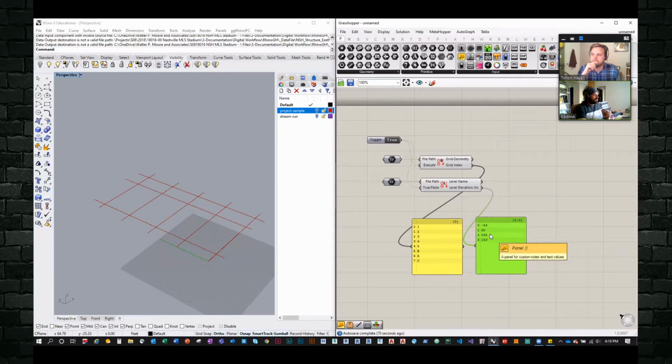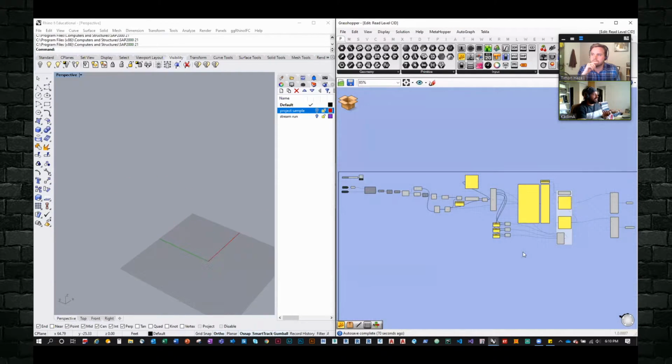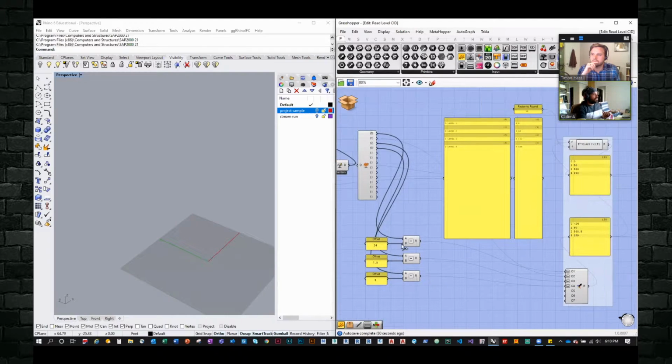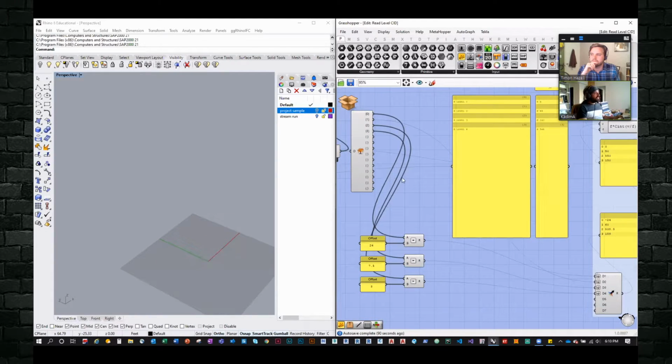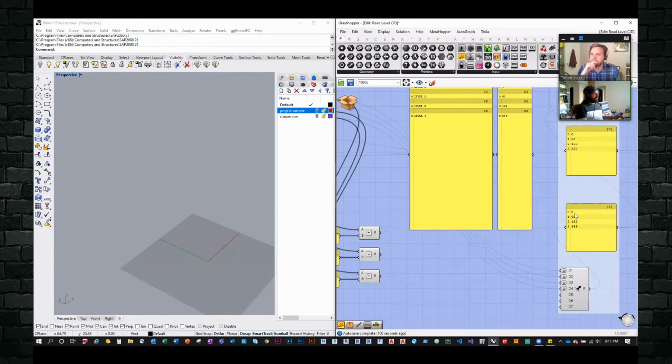Now you notice that the levels are kind of off. So what I want to do sometimes per project is dive into this cluster and study what my levels are doing. If the project manager or the project engineer I'm working with requires a specific offset from the level, this is where I consider those offsets. For right now, we're just going to simplify this and plug in the native Revit values so that I can just read those. And now they're organized from 0, 60, 162, and 546.